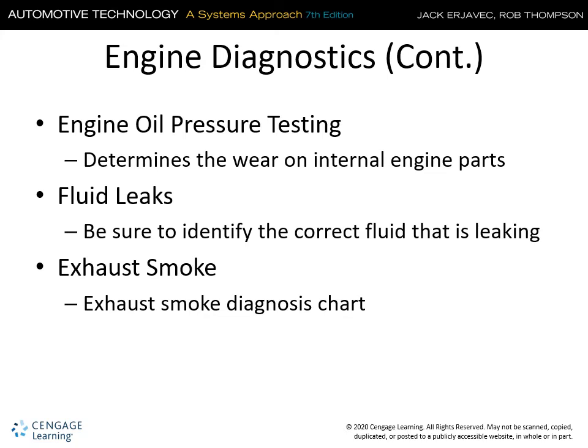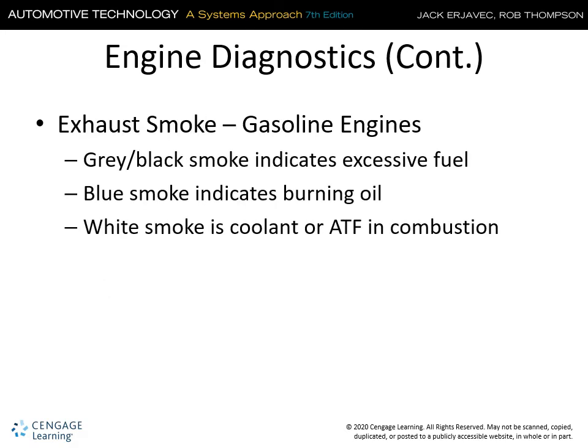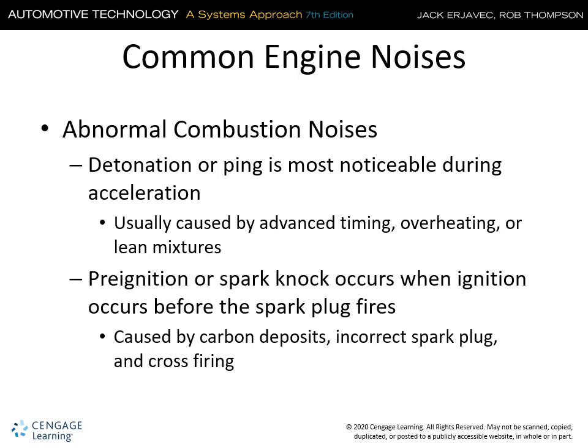We can also utilize fluid leaks and exhaust smoke. Gray and black is excessive fuel, blue is burning oil, usually coming from the valve train or through the rings, and white smoke is coolant or transmission fluid in combustion, either coming from an oil cooler or coming through the cylinder head or cylinder head gasket.